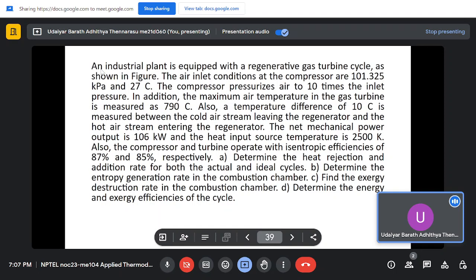So while solving, I have described both ways of solving. One is the process which is shown, and the other is using the ideal gas values. For example, for finding out the compressor work, you can use the reversible adiabatic compressor work to solve it, or you can straight away find out the enthalpies as I did in the problem.